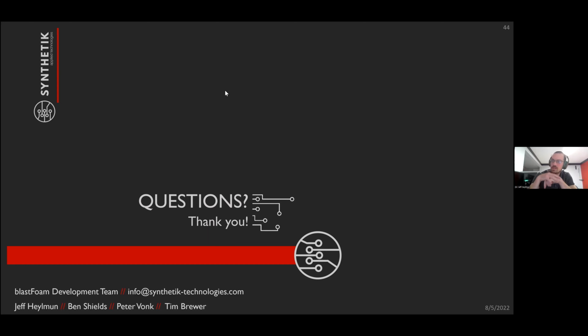Yeah, so we haven't done a ton of testing with it. We do have dynamic load balancing on, which greatly helps that. The main bottleneck tends to be at the start of simulations, where it forces all of the initial cells to be together. So if you have 1 meter cells, but you're refining down to like 1 millimeter, all of those have to be together.